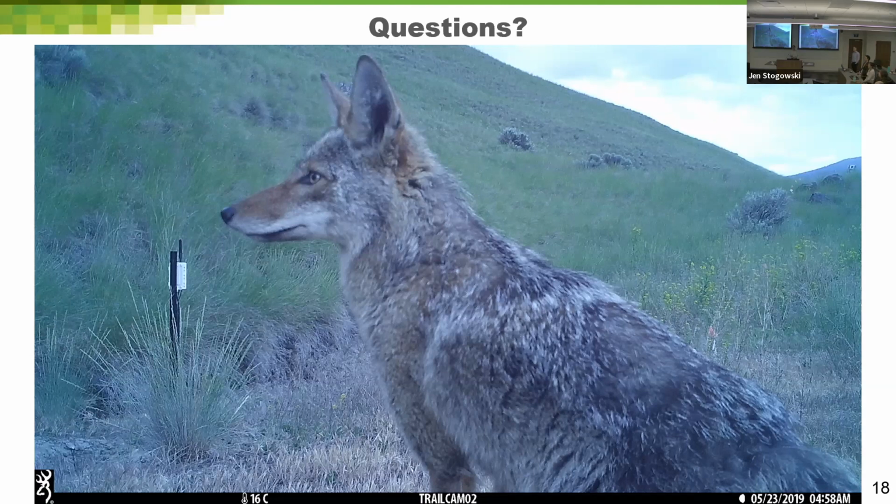The other problem is if you fill them in, how long is it going to be till they just open up again? You spend all that money closing them up, but I don't know how long it'll last. Hopefully sealing them up would slow them. After they did the little bit of investigative work a couple of years ago, the slope was reactivating and they reappeared within 4 months.